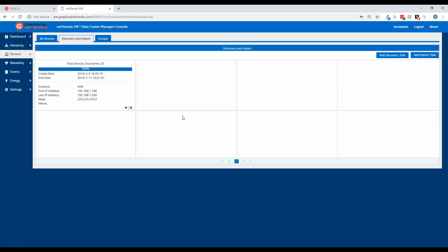If it's a PDU, you can monitor SNMP data. Depending on the PDU, you might get the power for each actual power connection or port connection. So everything that plugs into port 1 or port 2 of the PDU you can monitor individually or as an aggregate. So we allow you to do that discovery and bring that data back.